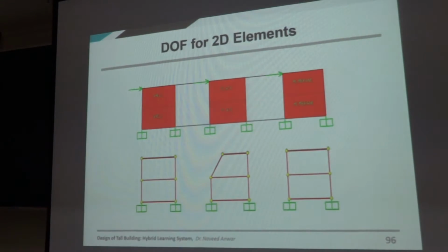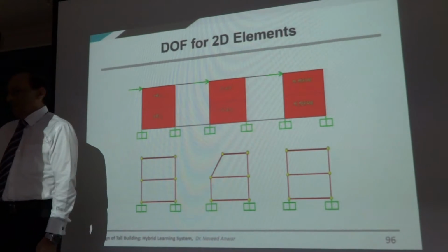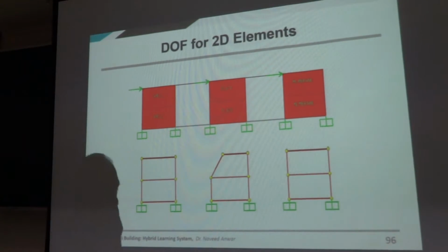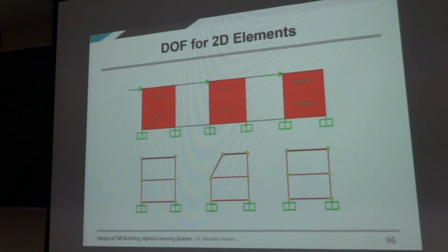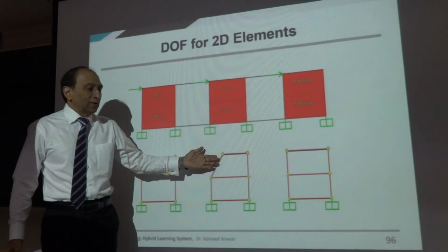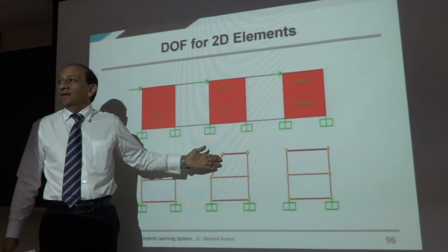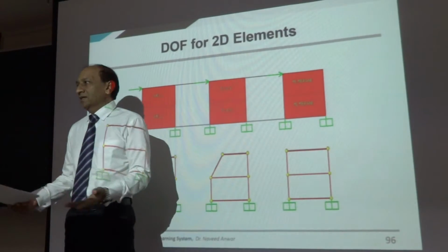This shows you what you can do if you apply horizontal load to a wall. So now basically I am taking this one like this, shear wall, you were saying, and I model it by 3 different elements by using membrane, shell and plate. This is what happened when I use shell, no problem, it can take the load. This is what happened when I use plate, because no in plane, it just runs away. And this is what happens when it's membrane, it stays there.